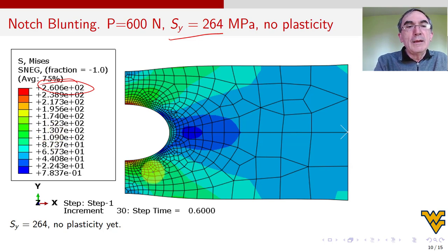Yes, you got it, okay? And the stress goes to 260. Sure, it shoots from 120 to 260 because Kt is 2.2, 2.19 we used in the previous video. So everything is fine, okay? No plasticity yet, I put here, right? No plasticity, no yield, all right?